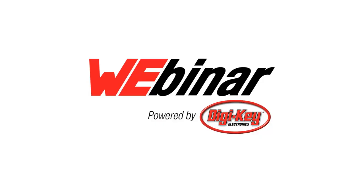Our next question: does trim sensitivity remain constant or does it change due to an aging effect? And by that they mean, does it change over time? Trim sensitivity, I think you mean what I call gain margin. Trim sensitivity is an amplifier's word for the same thing. So does an amplifier change its gain over time? I'm not aware of that myself. It does change over temperature, I can tell you that. Nowadays, people are starting to run circuits that go up to 125 degrees as a standard temperature range, and that's above 85 degrees. And I think in that 85 to 125 range, you're going to see some drop off in the gain of an amplifier, is my understanding.